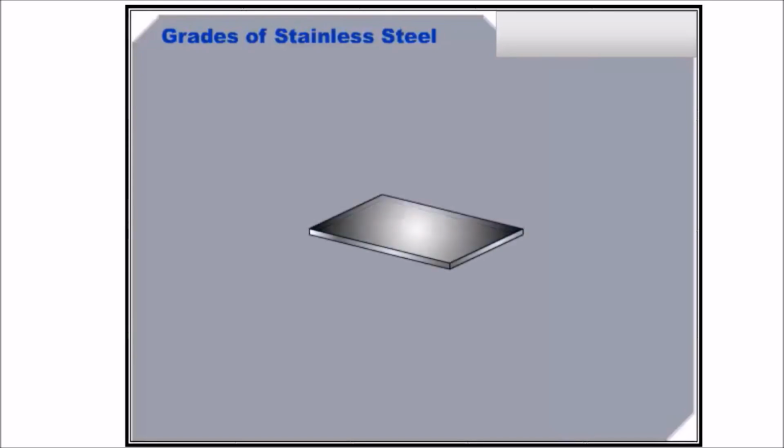The stable room temperature phase found in stainless steels depends on the chemistry of the steel, and some stainless steels may contain a combination of the different phases. The more common stainless steels are the austenitic grades, which are identified by the 200 and 300 series grades. 304 and 316 stainless steels are austenitic grades.